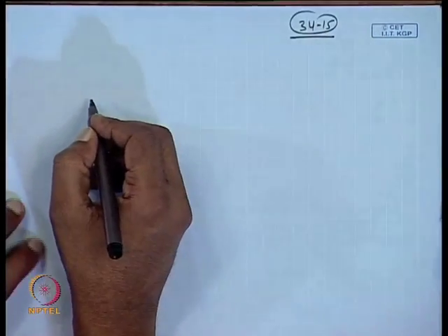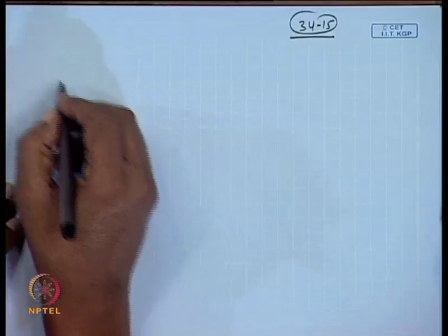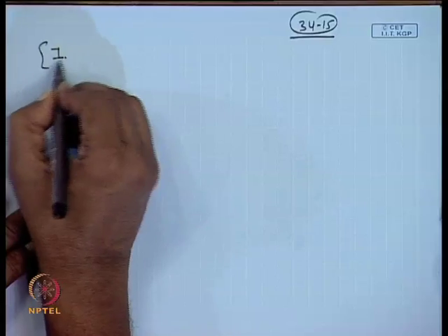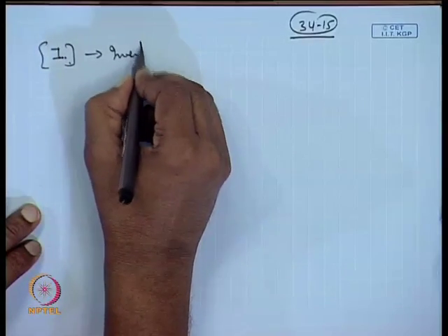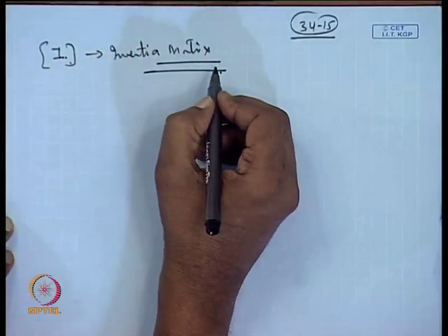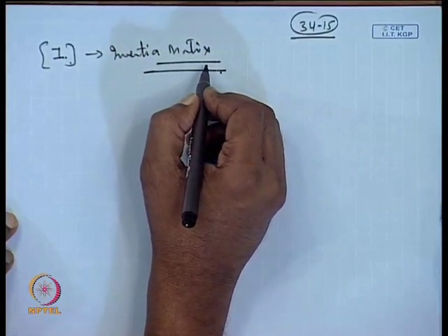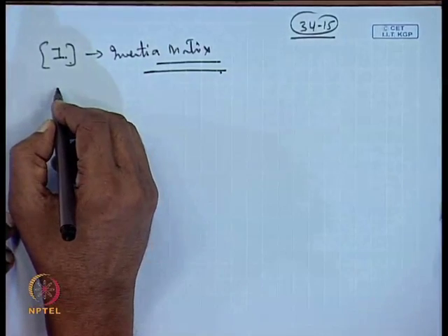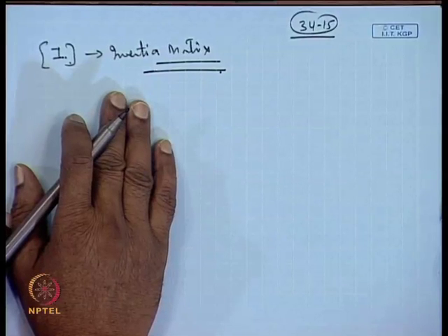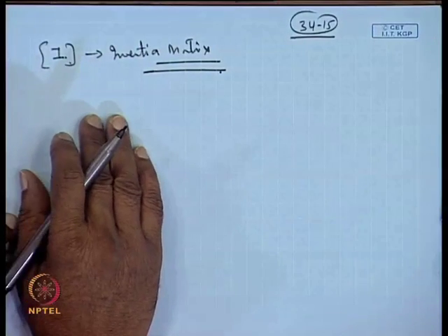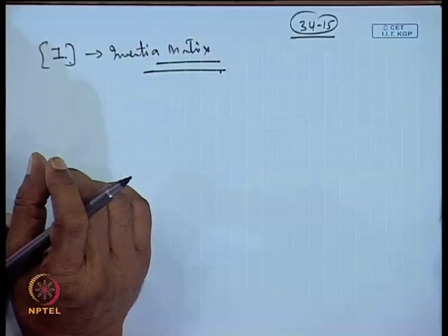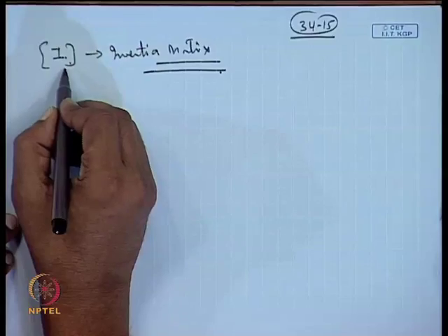We will list a few other properties also. If we are given the I matrix, which is the inertia matrix, we can list 3 principal directions of this, which will correspond to the 3 principal moments of inertia, which correspond to the diagonal elements of this.